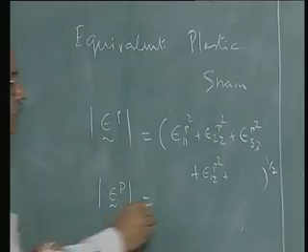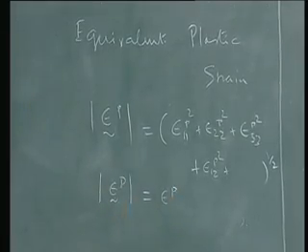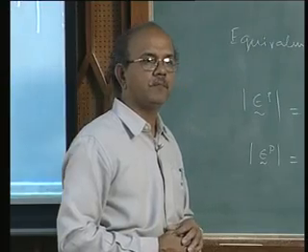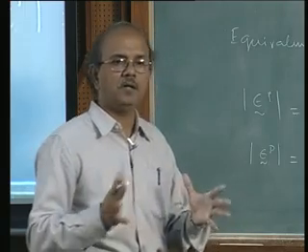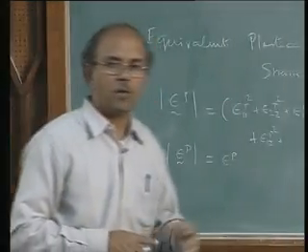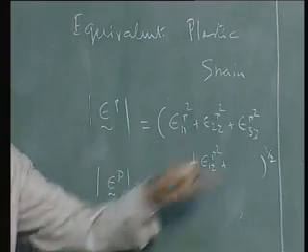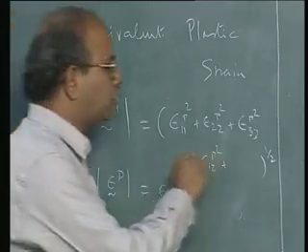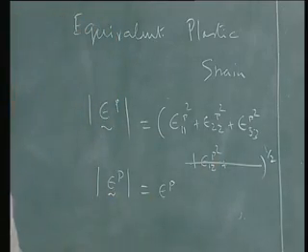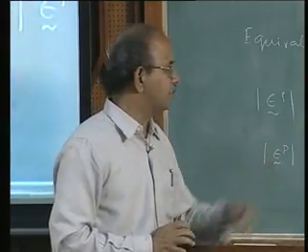But will it be so? How do I find that out? So, let us say we are subjecting this body to a uniaxial load. Now, what would happen to all these terms? Yes, of course, very good. So, ε12, ε13 will go to 0. I will not have all these terms. I will have the first 3 terms.